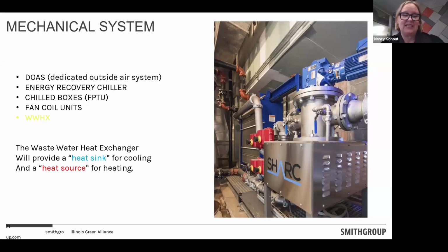So this wastewater heat exchanger is a heat sink for cooling. So in other words, it takes away heat from the system when we're operating in cooling, and a heat source for heating, so we can extract heat out of the wastewater to provide electrified, very efficient heating. Next slide.